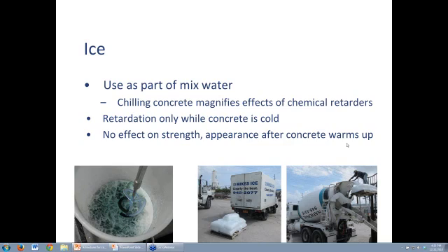It's really nice. And the great thing about ice is once the concrete's cold, you get it really cold. It's not dormant, but it's gaining strength slowly. It's setting much slower. You have all the time you need to place it, to finish it, to vibrate it, to do whatever. When you're done, you walk away, it warms up. Now it's at ambient temperature. That ambient temperature is hot, and now your concrete starts setting much faster. And it's setting at a comfortably accelerated rate. So you're kind of getting the best of both worlds, and ice is readily available, and it has no effect on the strength of your concrete.